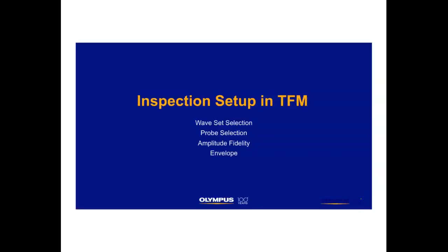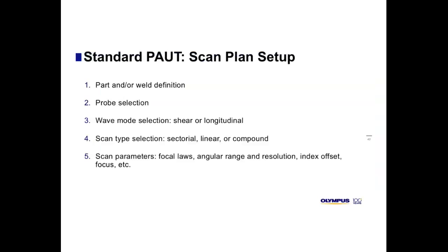Now, let's go deep with the setup in TFM, how we can make a setup in TFM, or what are the important parameters to consider when creating a setup in TFM. Let's start just with a quick refresh about the standard phased array scan plan. First, we have to define our part or weld. We have to select our probe.